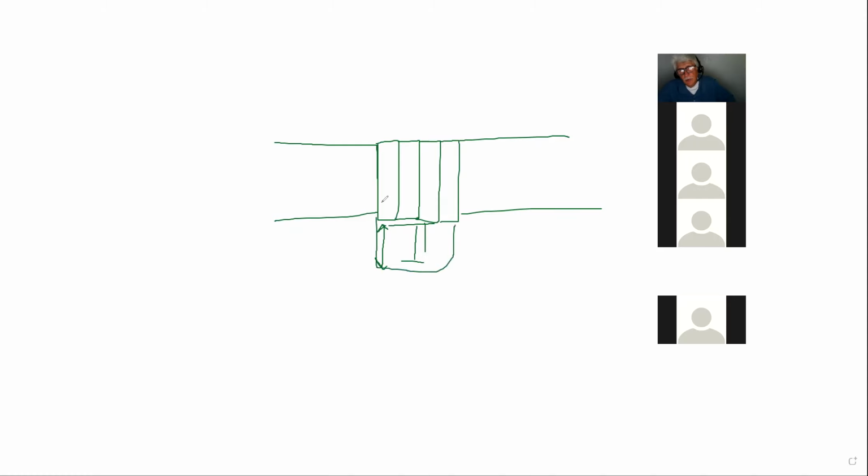But before you do this, I would still jack up the floor. You understand? Make sure that the floor is jacked up, then put the steel beam in. Otherwise, if you don't jack up the floor, if this beam is slightly overstressed right now, when you put this on and it starts to deflect, this thing is going to cause all kinds of cracks upstairs.